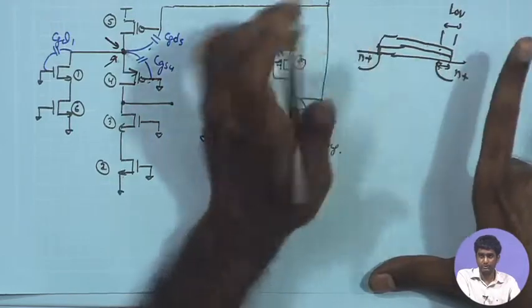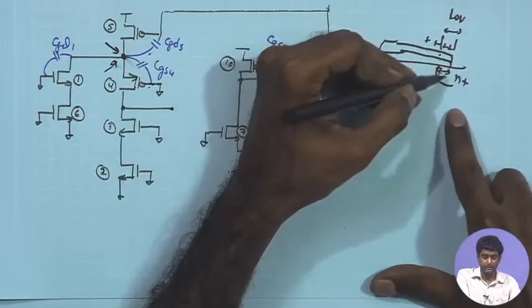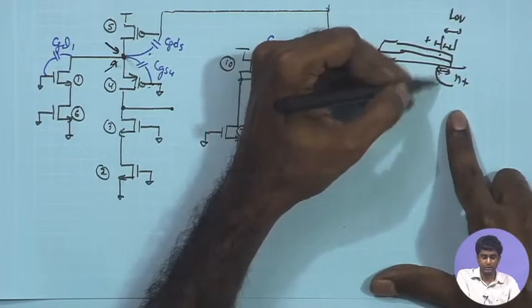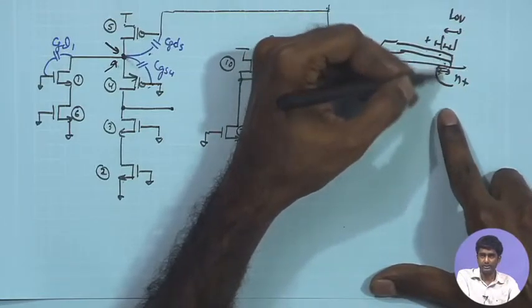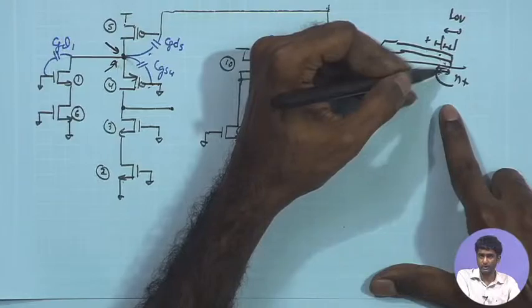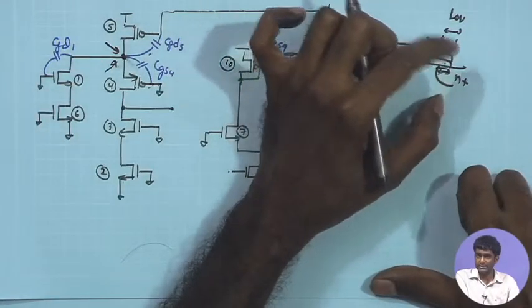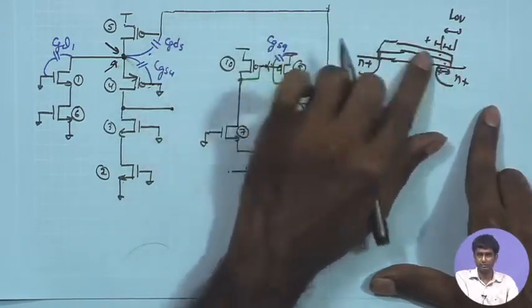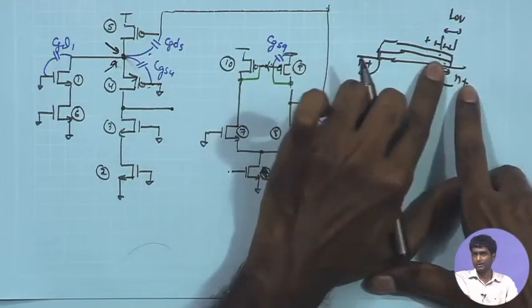the source region. Because when you are putting some more charges on the gate, the region just below the overlap is attracting more electrons, and therefore, some charge on the gate is balanced by the electrons getting attracted in the n plus region, where the gate is overlapping with the n plus. So, that leads to a fixed CGD component coming from C overlap. So, that C overlap component is present on both sides, and for saturation region the CGD is dominated by C